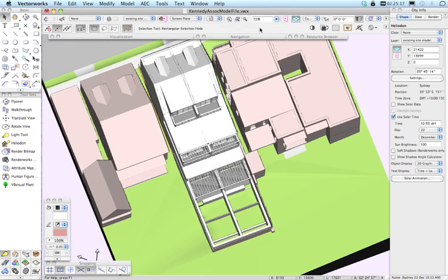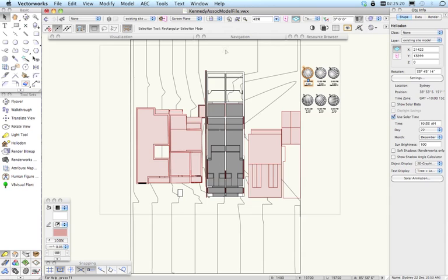So let's go ahead and click OK, and we'll just go back to the plan view here. What we want to do now, looking at 9 AM, is to cut a section through here. And if you do use solar time, then you need to specify that on the shadow diagram. And I think if more councils really understood what shadows were all about, then they would probably nominate that you needed to use solar time. But let's say we're not at that point yet, so we will turn on daylight saving, because that's going to be in effect in the summer solstice.